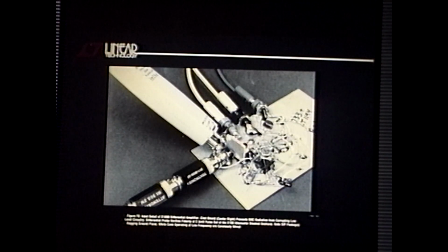That's a piece of copper clad right there. I'm worried about spray off the end of the attenuator here, leaping into the high frequency stuff. That's a shield. If I've got anything spraying off the end of this attenuator, any RF movement off of that thing, this will take it out. That's what that is. It's a piece of copper clad soldered across to stay out of trouble.